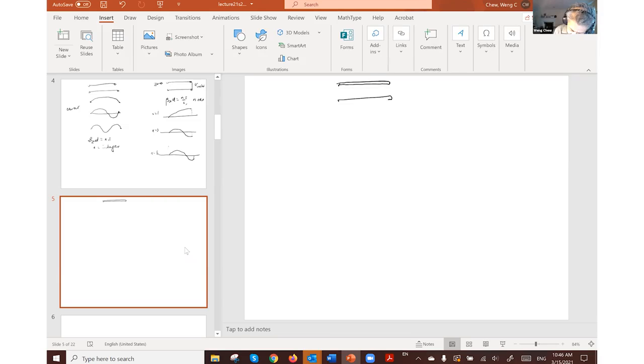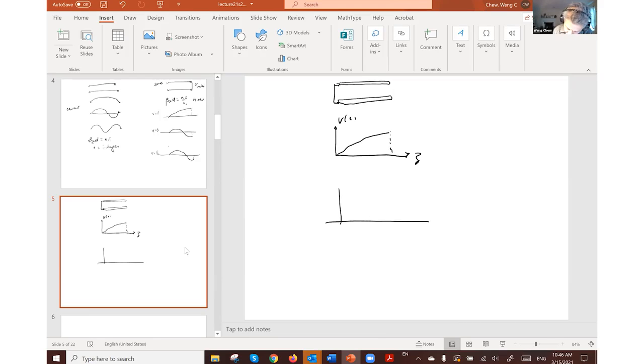That is when we have a transmission line with a short and an open on both ends, then you can actually plot the voltage as a function of Z. The voltage should be 0, and then will be maximum where the thing is open. Then the current would behave the other way around.